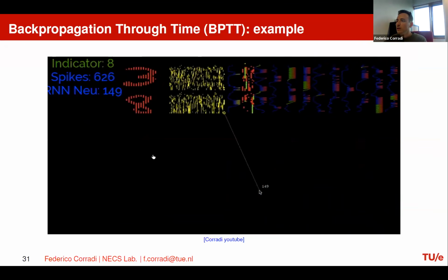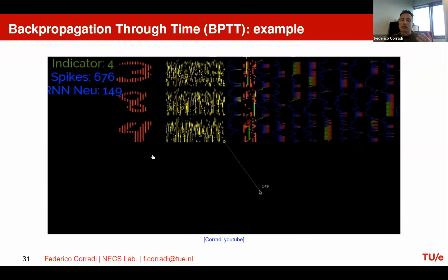And so what you see there is a simulation of activity that is run, for example, in the MicroBrain chip. You see here, the red ones are the spikes coming at the input. So we have 28 neurons on input. We have 150 neurons in the middle hidden layer with recurrent connectivity. And these yellow dots represent spikes from these neurons. So time here is going vertical, and neuron ID is horizontal in this case.